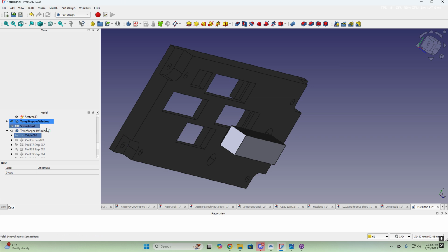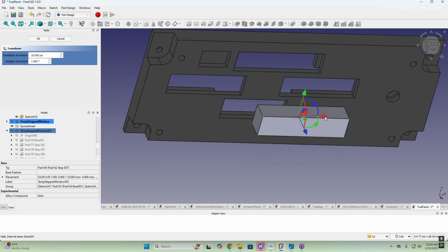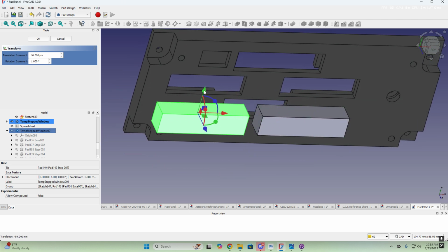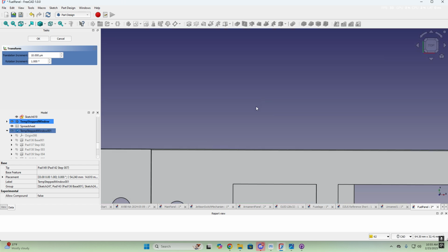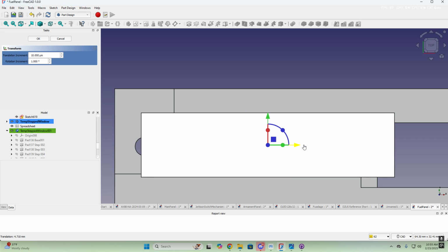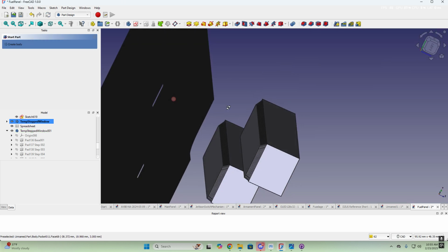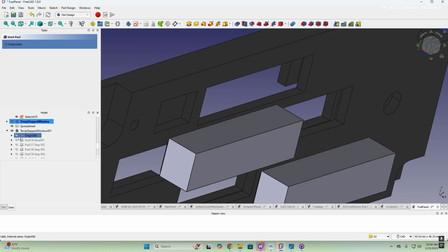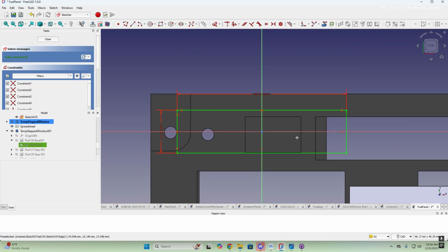If you want to adjust the values for a different piece, now here, let me show you this is a different one. So I'm going to move this off to the side. I'm going to hit transform, move over here, and let's say I want to do this guy here. So let me just line him up. Okay, I know that this cookie cutter is way too wide. So if I go to the base on this one here, I go to the very first sketch.